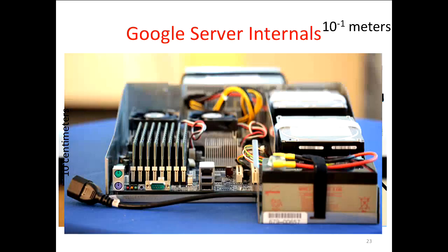The problem is if all of a sudden, Britney Spears gets hot for some reason, everybody's searching, all the Google servers go crazy. All of a sudden, you may want a couple more megawatts to power those important searches people are doing, right? And they can't raise the power consumption. What they do instead is not take it from the grid, but take it from the batteries, right? So they actually use the batteries to smooth out those peaks as well. And this was another reason they had these batteries, more than they probably needed for the battery backup reason. They could actually charge these at off-peak and run them at peak from the battery to stop pulling from the grid, all right? So at this scale, when you're dealing with tens of megawatts of power consumption, that power engineering is a big factor in data center design.